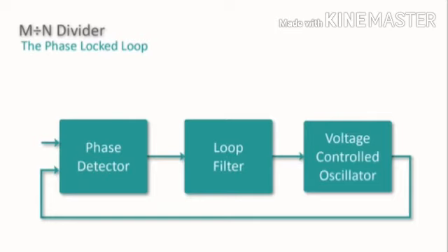Now, one common use for phase lock loops is for an FM demodulator. Think about it this way. If you apply a frequency modulated signal to the input, the phase detector and loop filter will try to push the VCO to track the input signal, and as a result, the amplitude of the output of the loop filter will track the input frequency and present a pretty good representation of the modulation waveform. This technique is currently the most commonly used method to demodulate FM signals in modern receivers.